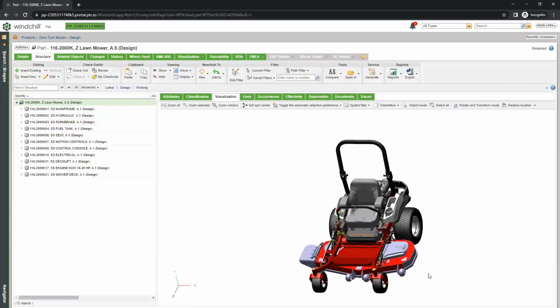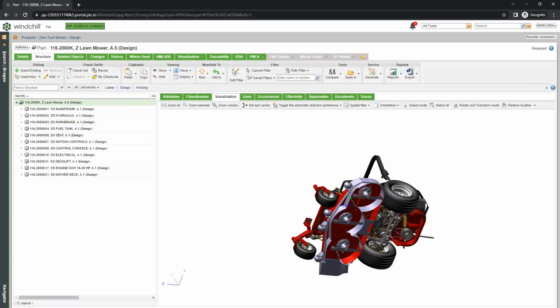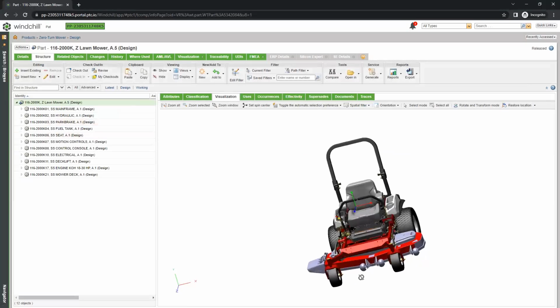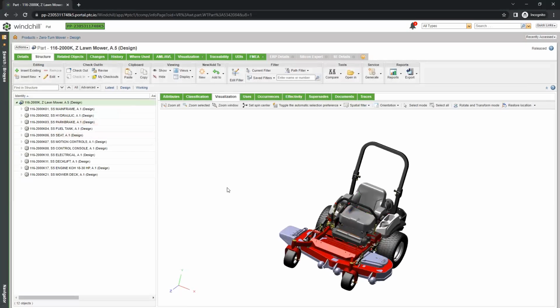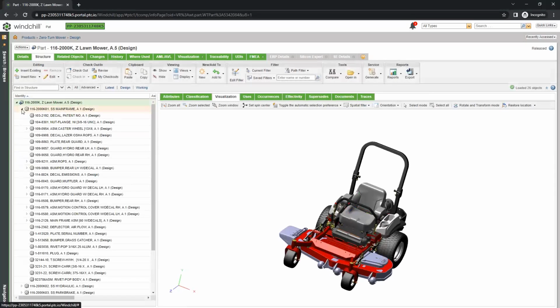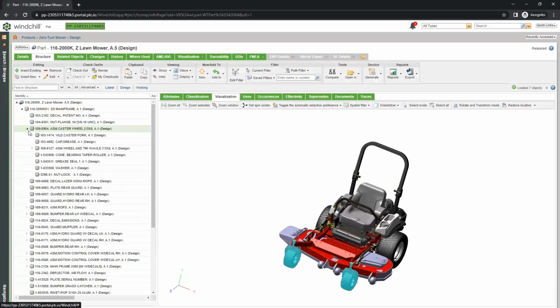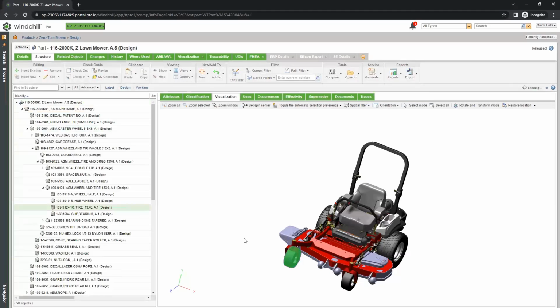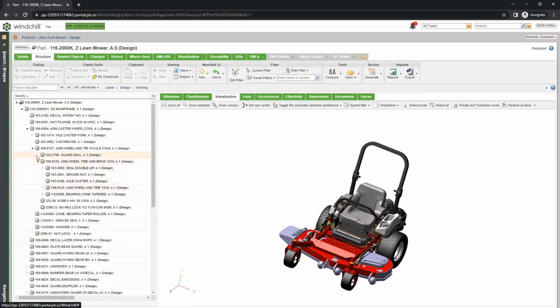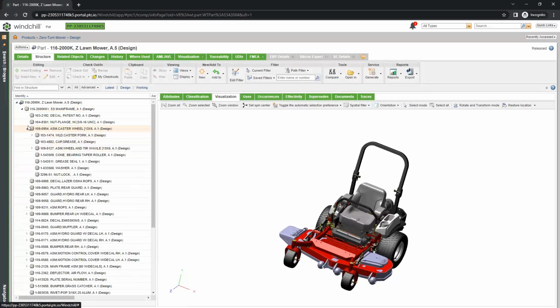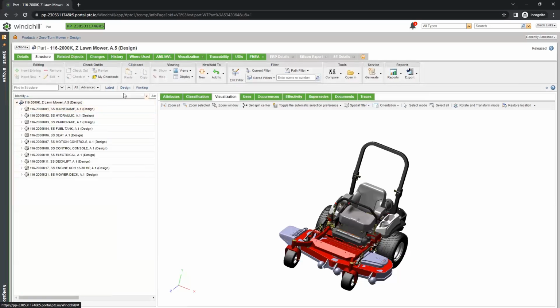We have lots of Creo data in here. There's SolidWorks data in here, CATIA, I think some NX, AutoCAD. And the reason that this is important is because inside of Windchill, we want this structure to be our bill of information. We want it to be the single location where we can go to and see not just Windchill objects in the structure like we're looking at here, those are WT parts, but actually see the related information. So dive into any one of those parts and see the individual files. And those files are really where we're getting into the data from the different systems.